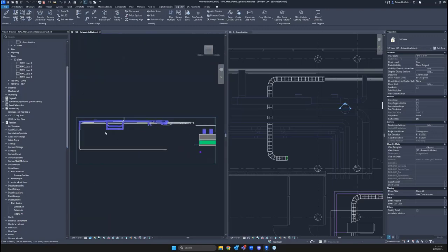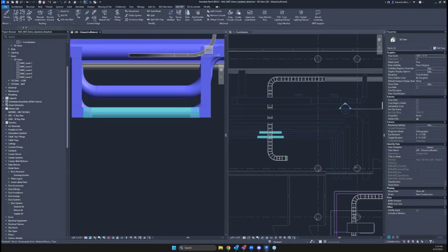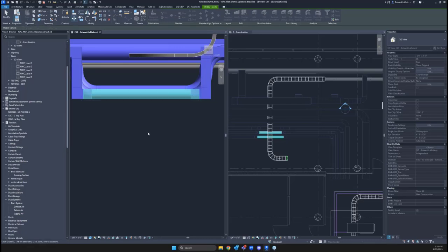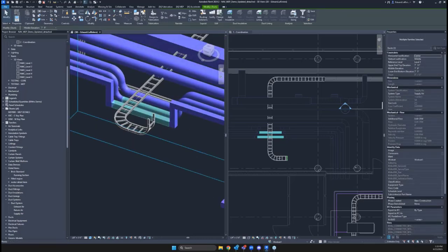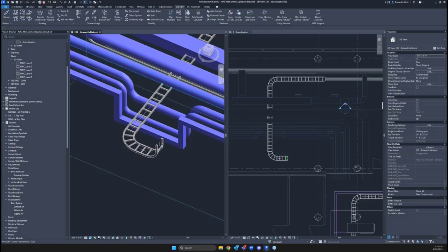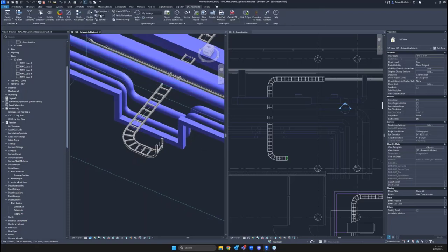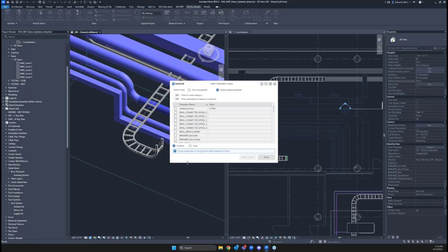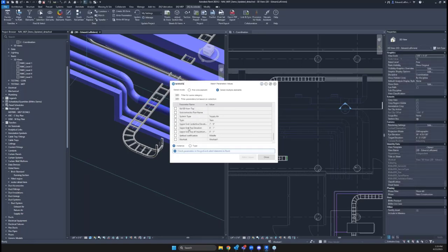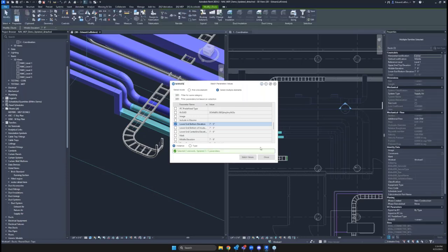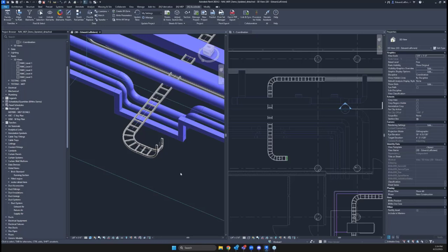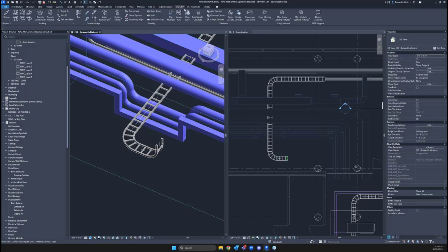Just like before, we can snap ourselves to the left view, grab all those items and use the move command to make them all the same bottom elevation. Maybe you're not a visual person though. A quick tool inside Accelerate called match parameters could let you grab a host element, and maybe you want to get the lower end, bottom elevation there, great. Let's grab two other elements and just match those values together. So there's lots of tools in the MEP, but there's also tools in Accelerate that support those workflows.